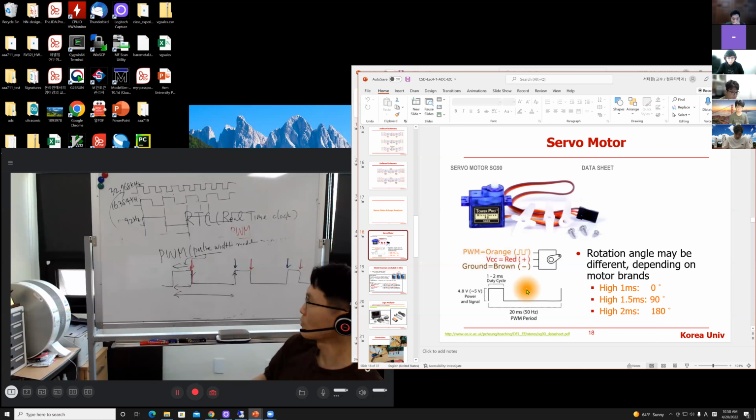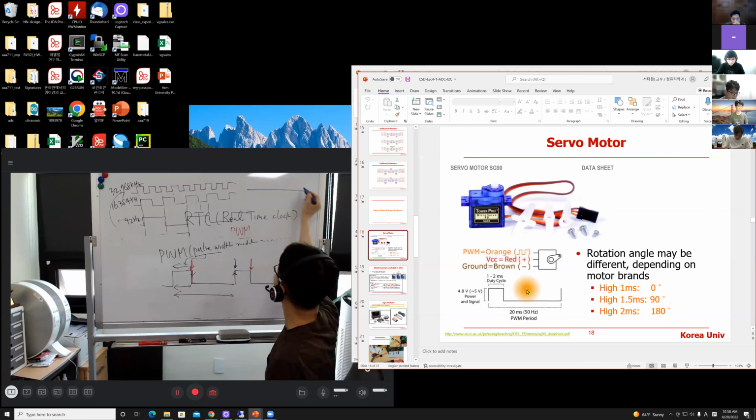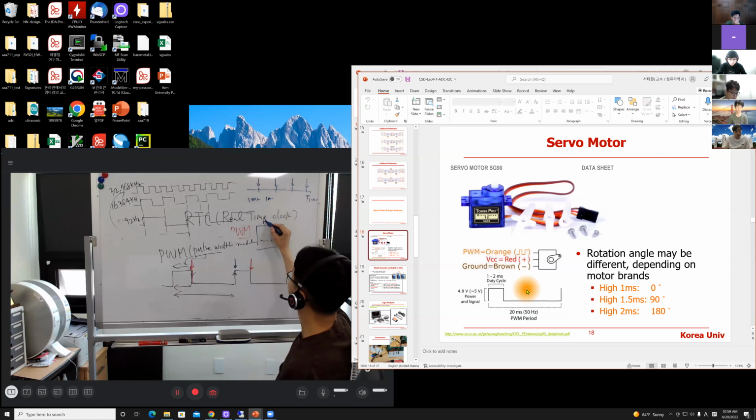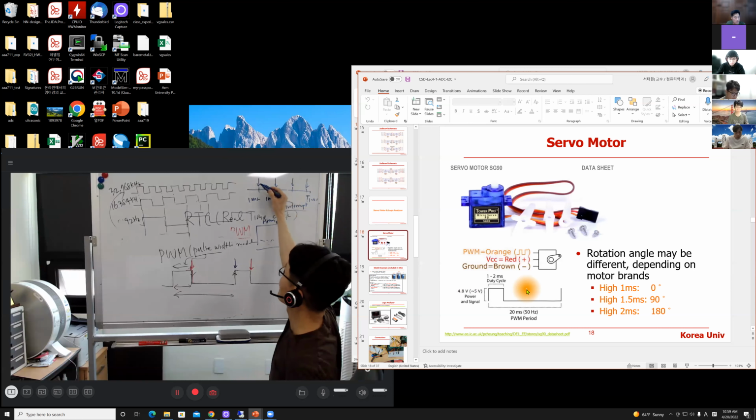How does the CPU know? Think about that. Every 1 millisecond, 1 millisecond, 1 millisecond, this is the time to schedule a new task. You have to let the CPU know through an interrupt. Don't worry too much about interrupts; we'll talk about that after the midterm exam. Anyway, the timer is generating a periodic interrupt like this.